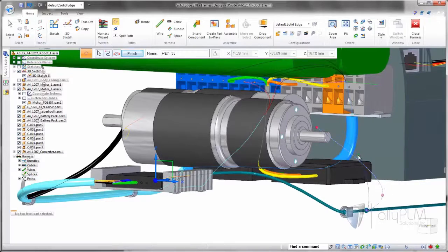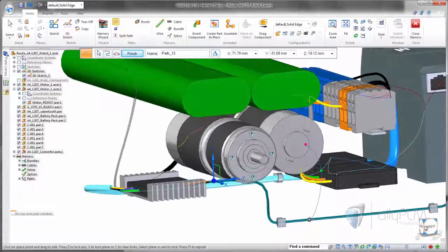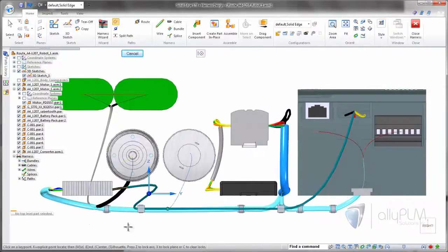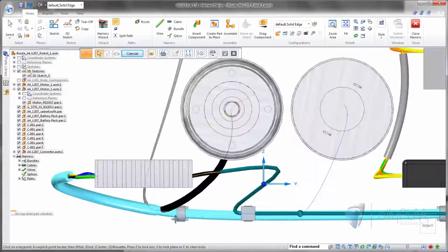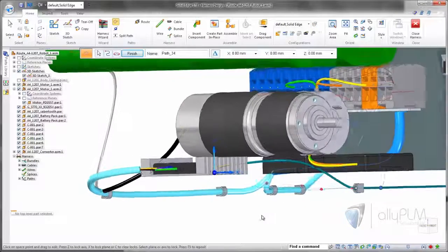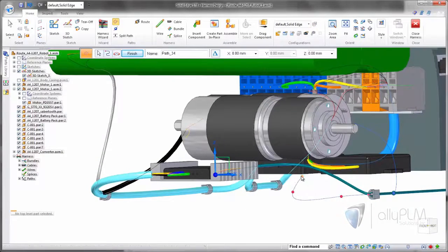Notice that routing a 3D sketch allows us to easily get our desired results in a fraction of the time. Using the control point and blue dot created on the splitting path makes an appropriate anchor point for our two new paths to complete the run. Using new paths that connect to a split allows users to bundle several runs together to create a desired harness.